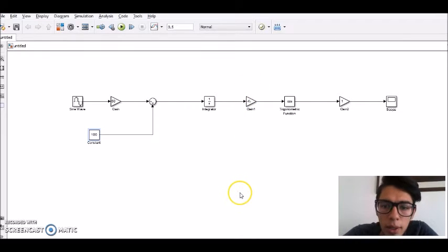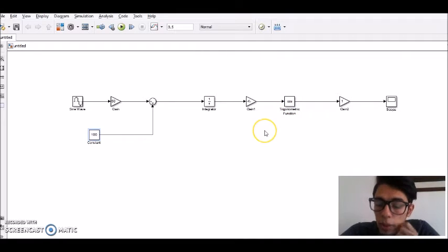For the signal, we need a function, more specifically a cosine function. So we find the block diagram in the library browser, drag the block, and double click to edit it. Then we drag the arrows to connect each one.